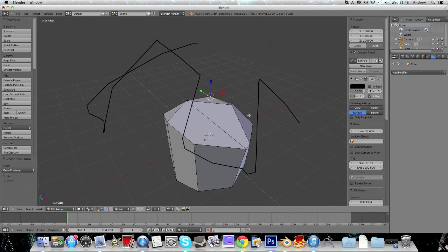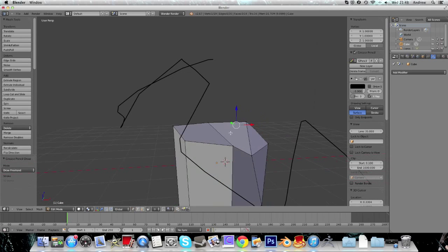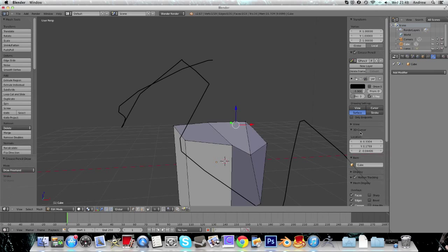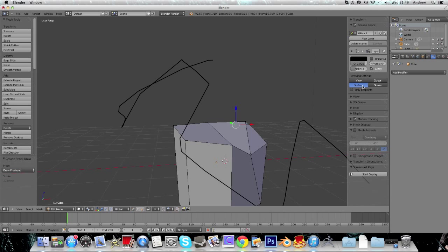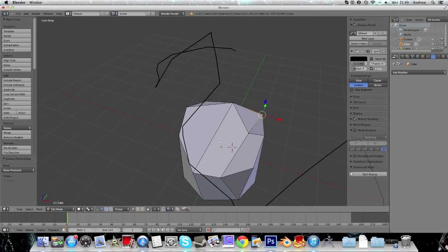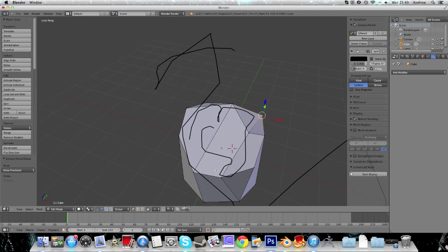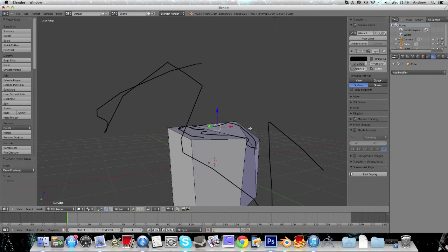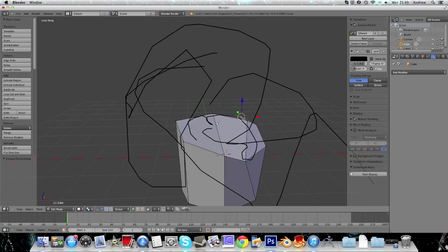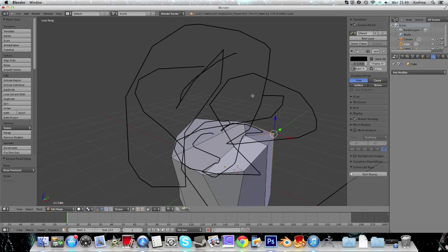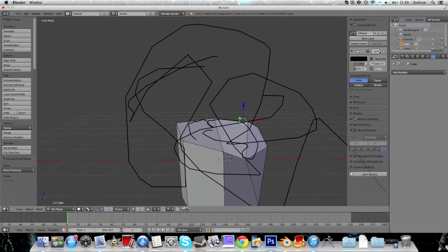I might have some different settings on. See, I've got mine set to surface over here on the right, so I'm going to close to the grease pencil. We can see that I've got it set to surface in the blue here, and all that means is when I draw with D, I'm actually drawing onto my shape. So I'm drawing all around here, and it's being stuck to the surface. Of course, if I'm drawing off the shape, then it's going to be drawn to my view, which is exactly what the other setting is. So I draw it to the view. It's going to draw it roughly in the center, and I'm drawing around, and then I rotate, and it's rotating with your view. I'm going to go ahead and delete this now.